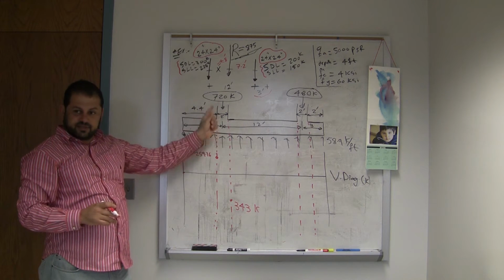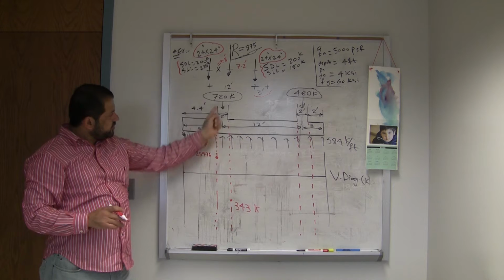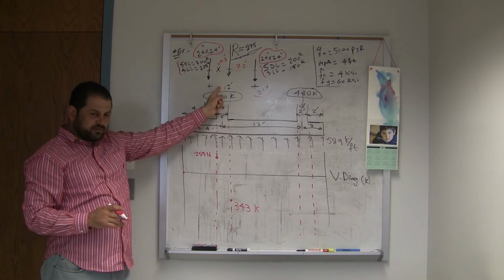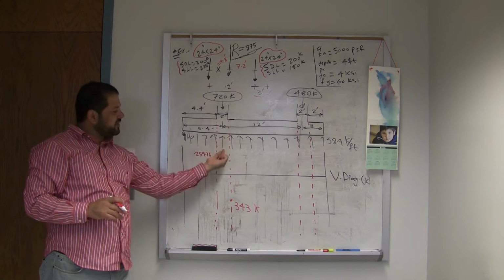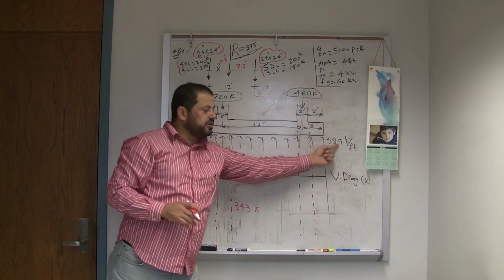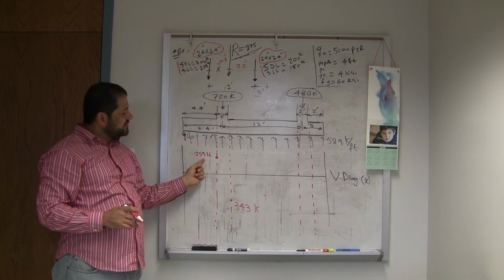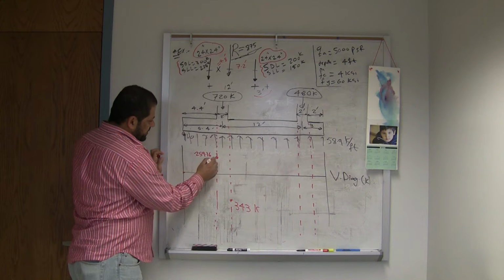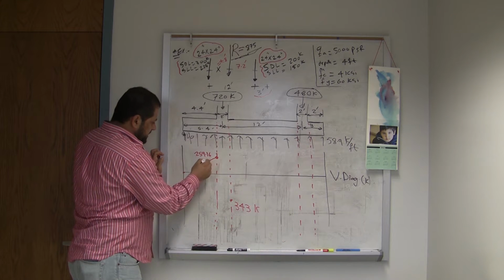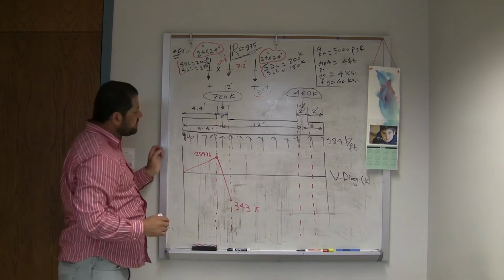Again, usually students make a mistake in here. You go down by the reaction or the load on the column, but don't forget that the width of the column also has underneath it 58.9. So also there is 58.9 times 2. It adds to that, then you subtract that here. So this is constant, and this is linear. Then you go down to this guy in here.